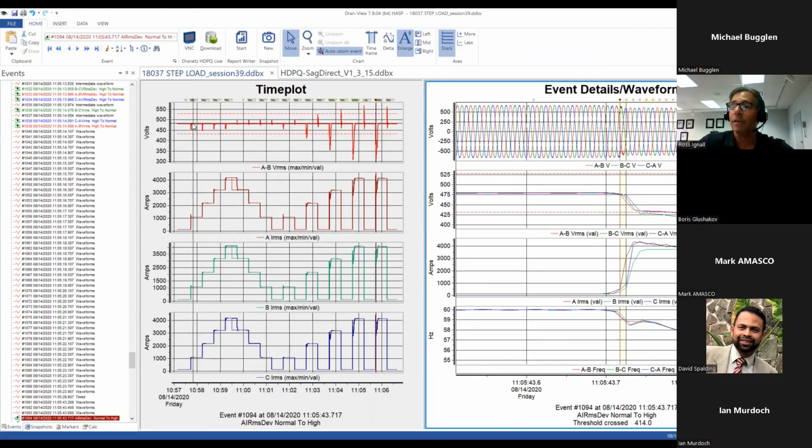This is the impact on the voltage. You can see in this example how the voltage is fine. Typically when you get to these impulse tests, 0 to 50%, you can see it starts getting around the limits, which I believe here are plus or minus 10% of nominal. So you can see the impact. A very important thing when you're running on generator is what the impact on frequency is.